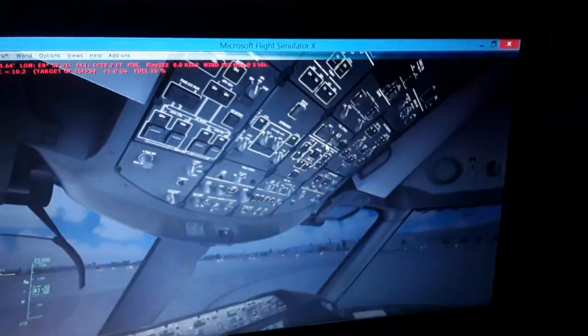And also the aircraft will be flying with an airspeed like 2 or 3 times faster than at sea level. So we're going to have a higher intake of air from the front fans of the engines for compression and combustion. This also controls the fuel-air mixture, which is going to be different as we climb from sea level all the way up, or vice versa as we descend back to sea level. So we have the FADEC, the full authority digital electronic control computers, to control everything for the engines, also engine start, engine shutdown, fuel-air mixture. So it's a good thing to have the FADEC installed in your engines.